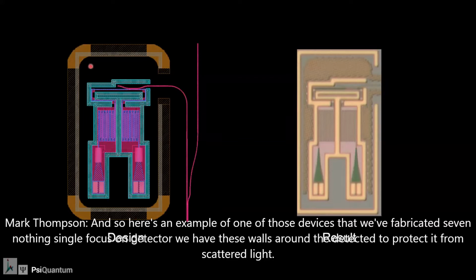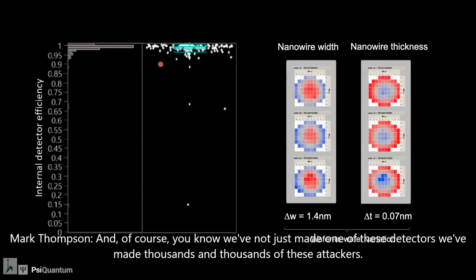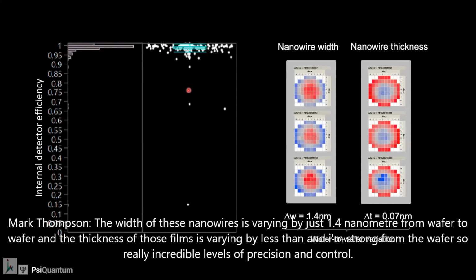And so here's an example of one of those devices that we've fabricated, a superconducting single photon detector. We have these walls around the detector to protect it from scattered light. And of course, we've not just made one of these detectors, we've made thousands and thousands of these detectors. And here's an example on the right showing hundreds of these detectors characterized, with over 98% of these devices giving greater than 90% efficiency. And on the right, you can see the levels of precision and control that we can get. The width of these nanowires is varying by just 1.4 nanometers from wafer to wafer, and the thickness of those films is varying by less than an angstrom from wafer to wafer. So real incredible levels of precision and control.